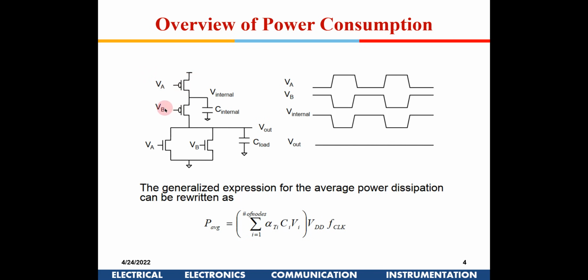So if a particular signal A is going to remain off for a long time, I might put it here, right? So if A is switching high and B is switching low, what will happen is this node will unnecessarily keep getting charged high and low. We are not even interested in this particular node. So even for the PMOS circuit also, this particular concept is applicable. Okay, so there it is NAND, here it will be NOR.